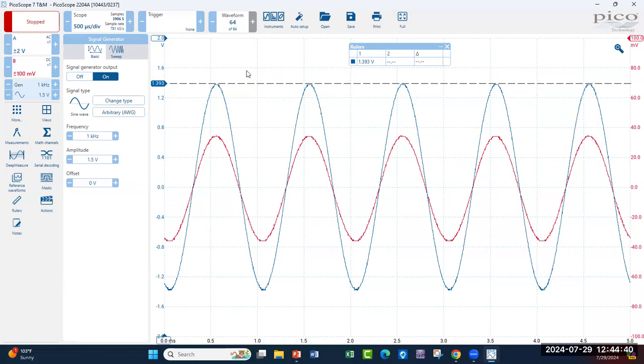If you see this right at the input, because channel A, this dark blue trace, is my input, directly hooked up to the signal generator, and my signal generator says it's supposed to be putting out 1.5 and I'm not measuring 1.5 on the board, then we need some compensation. We talked about that before. So the first thing, before I go comparing any wave shapes, is I've got to get my V peak on my input to be accurate with respect to the design parameters.